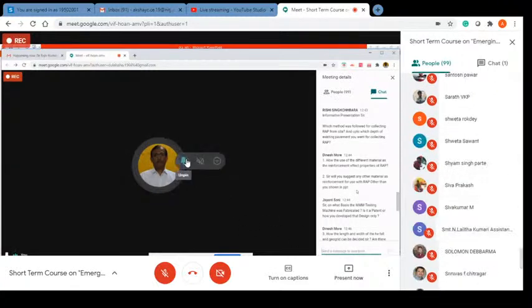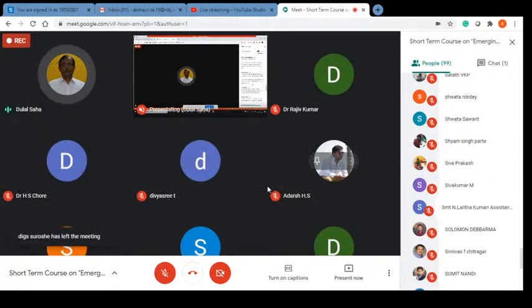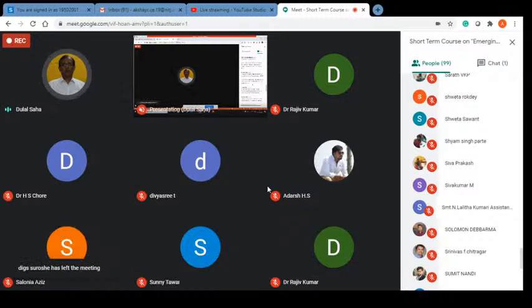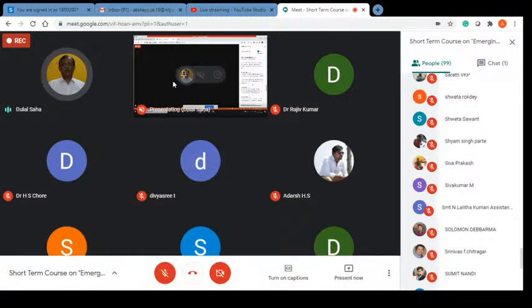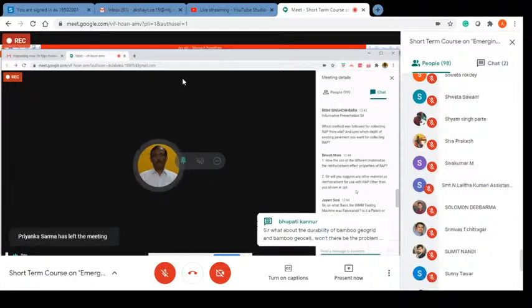The first thing I tried was to add geogrid also, just to see. It is something like I try to put the load uniformly. I mean, the functions of geocell and geogrid are completely different, as you know very well. But I wanted to put a uniform level, strong surface, and then allow the geocell to function to its fullest. That's why I have used these two in combination.